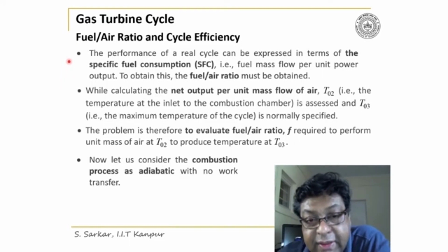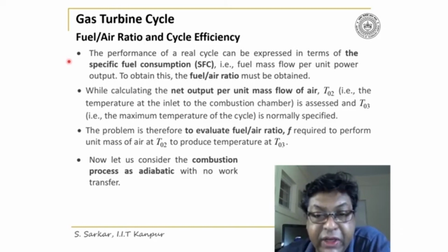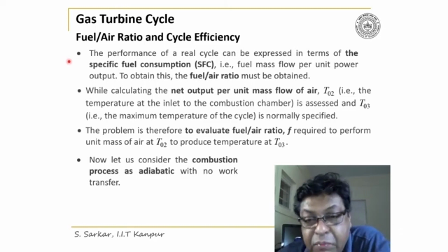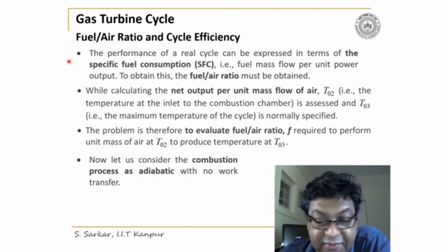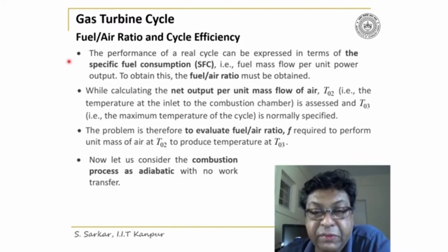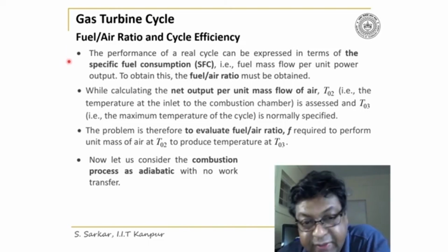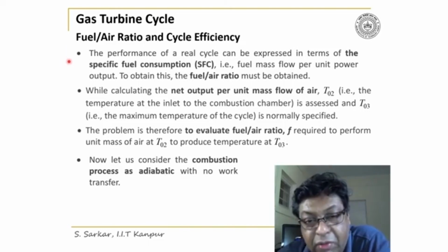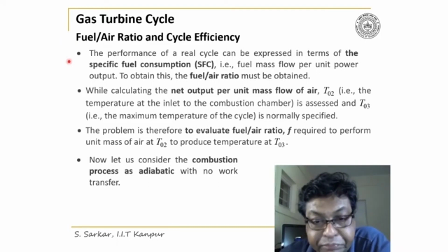Thus, the specific fuel consumption is the fuel mass flow rate per unit power output of the cycle, that is, fuel consumed per specific power output of the cycle. Now I'll show you how to evaluate fuel air ratio for the cycle.